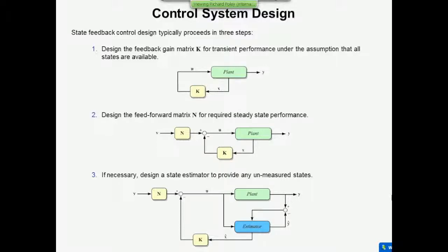Now, recall that K fixed the controller eigenvalues, the closed-loop control eigenvalues, and that the estimator had its own set of eigenvalues, which is bound to influence the closed loop. So you choose the estimator eigenvalues to be faster than those you designed when you designed K. Well, who's to say that inputting an estimator in the loop that you haven't changed the closed loop eigenvalues? Who's to say that? All I've shown you is how you design the closed loop knowing what the state vector is, and how you've designed the state estimator to have its own eigenvalues. Who's to say that putting these in didn't influence the ones you chose from K?